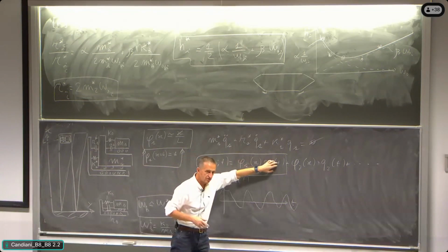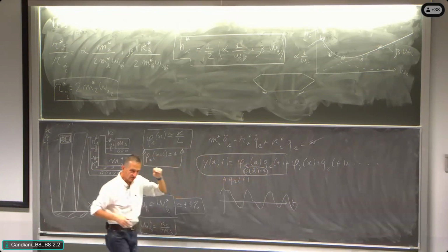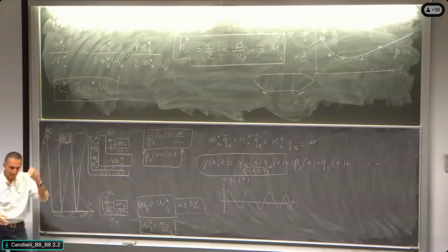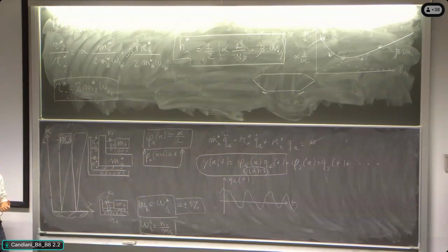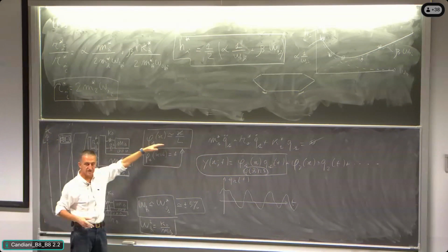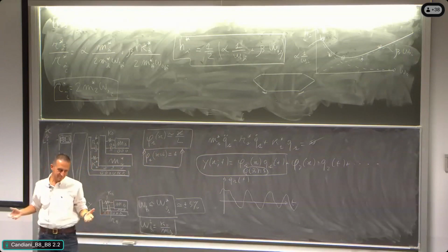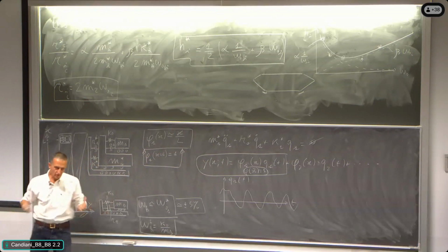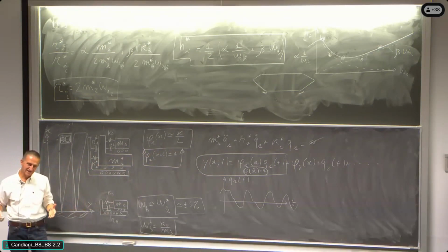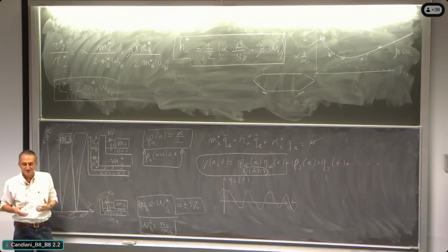The principal coordinate Q1, now, with this normalization, has a very physical, practical, evident meaning. It is the movement of the top of the building. That's it, it's finished. Making a normalization different than that is possible, but it is, I would say, stupid, not useful. Let's say it is making us have troubles instead of giving us a simple way of thinking, all right?